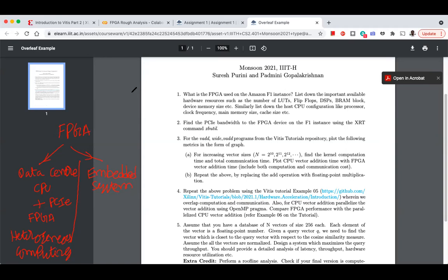Okay. Second is the embedded systems space. Usually, the FPGA programmable logic and the programmable system, the CPU and FPGA, are closely tied within the same chip, so to speak. PL stands for programmable logic, where you can keep whatever custom circuit you like, and PS stands for the processor. Usually ARM processors are present.